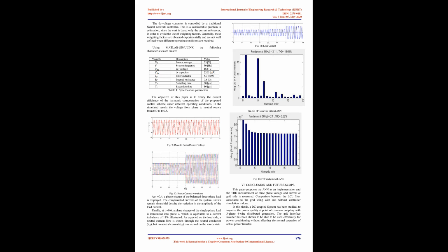Using the ANN controller provides a quick response by reducing the rise time by approximately 33% as compared with the PI controller. Fig. 5. Schematic diagram of Adaline network. This schematic diagram consists of two levels, named as input level with n inputs and one output level with two outputs, and a multi-layer feed-forward Adaline neural network is used.